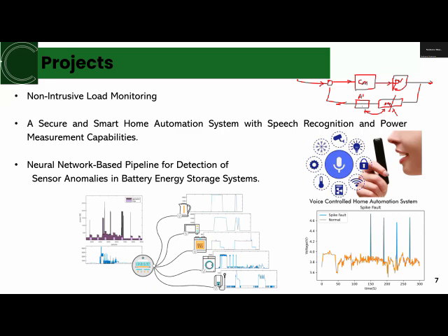Later on, they identified that the current sensor was faulty. It was not giving the correct value. During that issue the current value went abnormally high, and due to that the temperature also rose. But the sensor installed to monitor the battery bank's input or output current was not functioning properly. So the control system thought nothing was going wrong and didn't take any preventive measures. All of a sudden, it blasted.